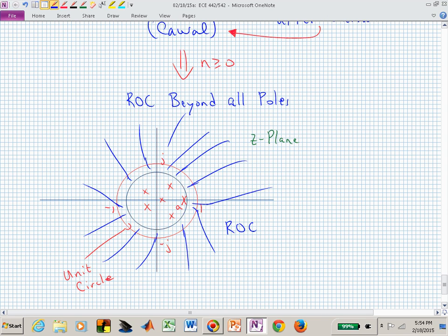It's the one that's in red, and for our systems to be stable, we need all of those poles inside the unit circle. We can still have Z transforms that have poles outside the unit circle for a causal system. It will be an unstable system. That's okay. Then we'll have to stabilize the system with a controller. But for stability, we want to put all of those poles inside the unit circle. The closed loop poles, if our open loop poles are not there initially.